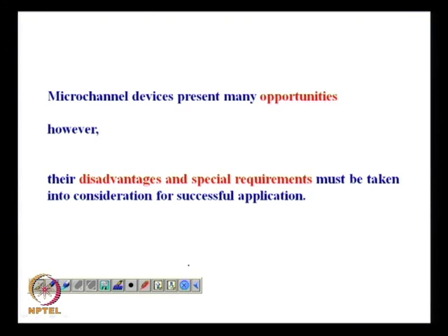The major disadvantage that one should think of is the pressure drop. How do you control the pressure drop? What would be the effect of pressure drop? How do you ensure that you have the same amount of flow through all the channels? That is, the designing of the manifold in these cases is extremely important. How do you distribute? So, the design of the distributor is extremely important.